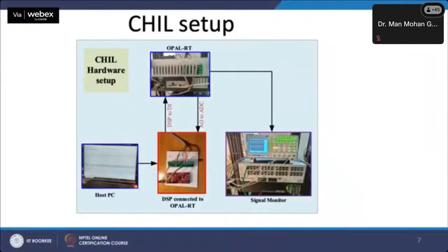To perform active balancing, one should determine three major factors: first, mode of charge distribution, for example, direct cell to cell, adjacent cell to cell, energy sharing; second, balancing topology, that is type of converter, boost, buck, flyback, half bridge; and third is balancing strategy, that is what type of control logic parameters need to be taken care of, for example voltage, OCV, SOC and SOH.